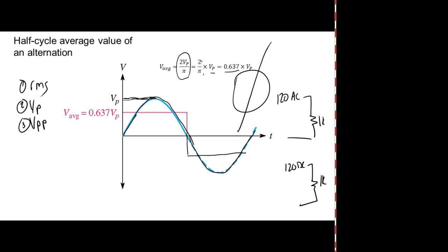Why do we have to use RMS and why can't we use an average? Because if I used an average of the positive and the negative peaks, it would always come up and give me 0. Because every positive value has a what? A negative value that cancels out. So we came up with a method called root mean square. So RMS stands for what? Now mean is another word we use for the average. And then square. That's what it stands for, but what does it mean?